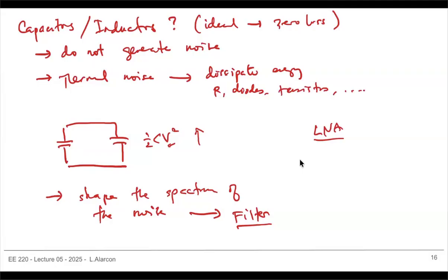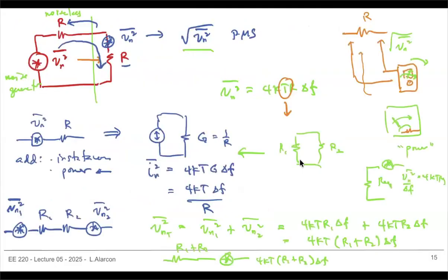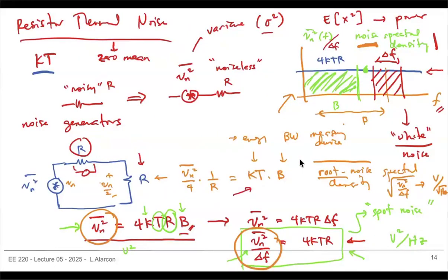That's a bad idea because, as you can see here, if this is the only bandwidth that I need and I overspec, I actually get more noise. Right? So it turns out I can filter noise by limiting the bandwidth of my amplifiers. To make it easy later on, a lot of the real amplifiers we'll look at have noise specifications.